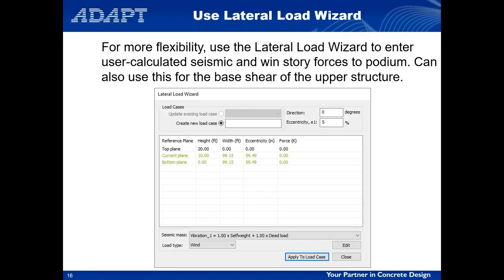There's one question that was just asked: how would you apply the wind load to the upper wood structure? That's a good question. Remember we started out the session by saying you have those lateral loads that are defined as couples. The default scenario is that you have a set of couples for your seismic and for your wind.